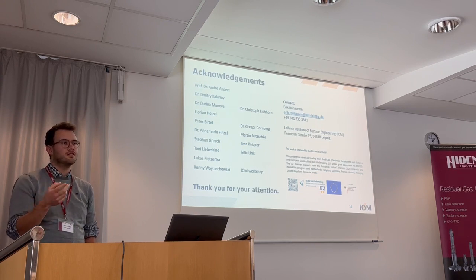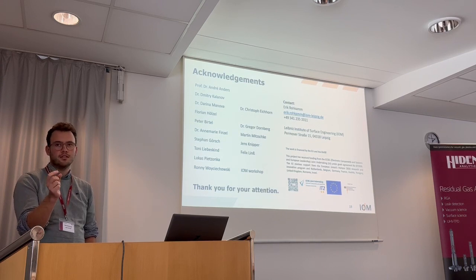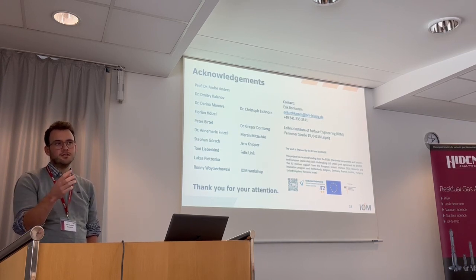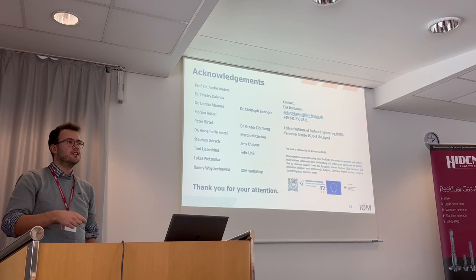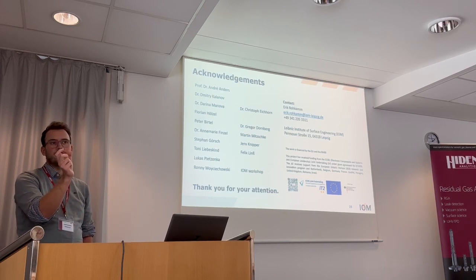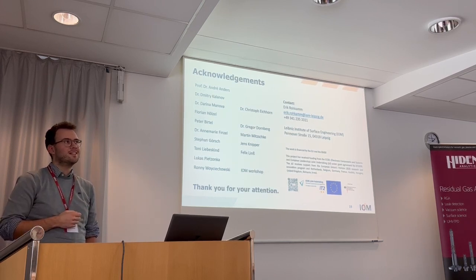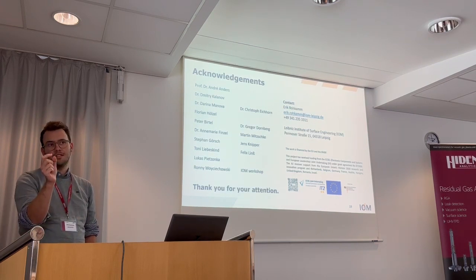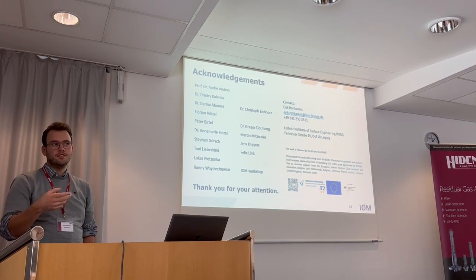So we have to take care of our orifice. We start with a 50 micrometer orifice because it's the smallest. We need to lower our intensity, and over time we see an erosion, so a widening of our orifice. I think in the worst case it was 700 micrometers afterwards. So we really need to replace it